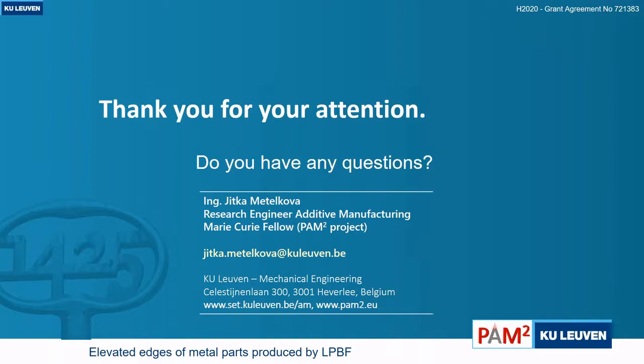First of all, you use the processing laser to reduce the elevated region and a femtosecond pulse laser, right? Yeah, the femtosecond pulse laser was ex situ, it was post-process, so you have quite some positioning on the stage, and it takes some time to set up. But the idea is that now we also have it in situ, and it's not a femtosecond, it's a nanosecond laser that we have in our machine.